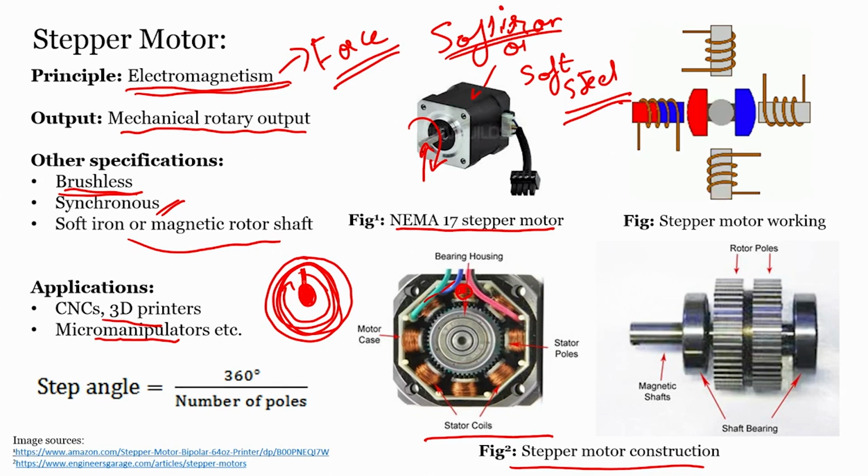But in a stepper motor, it happens in steps. Like this is the shaft, and this was the line. It will rotate and come over here first, then here, then here, then here, then here, and here, and it completes a rotation. Though I showed it like 8 different motions, it's actually very continuous in the sense that once we give the signal for rotating it, it will rotate in steps, but the steps will be close enough that we will not feel like it is a step by step motion, but it will be continuous. But this is how it works.